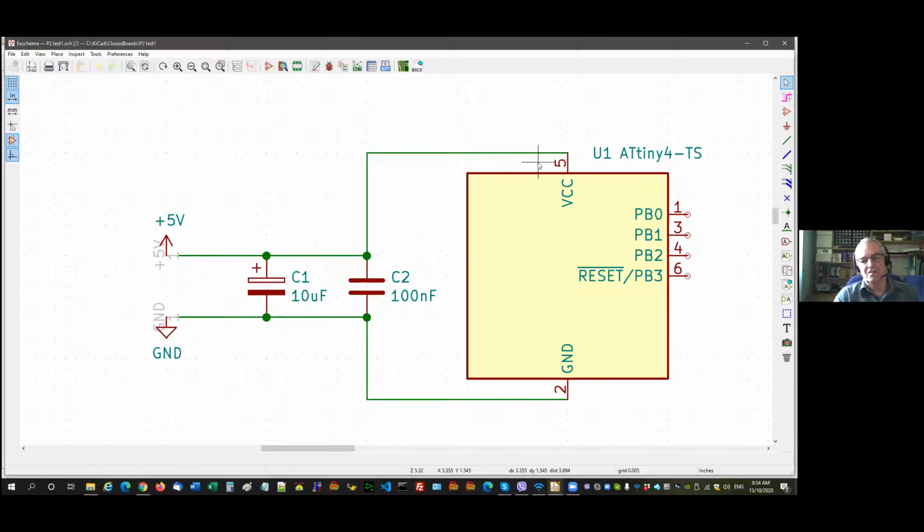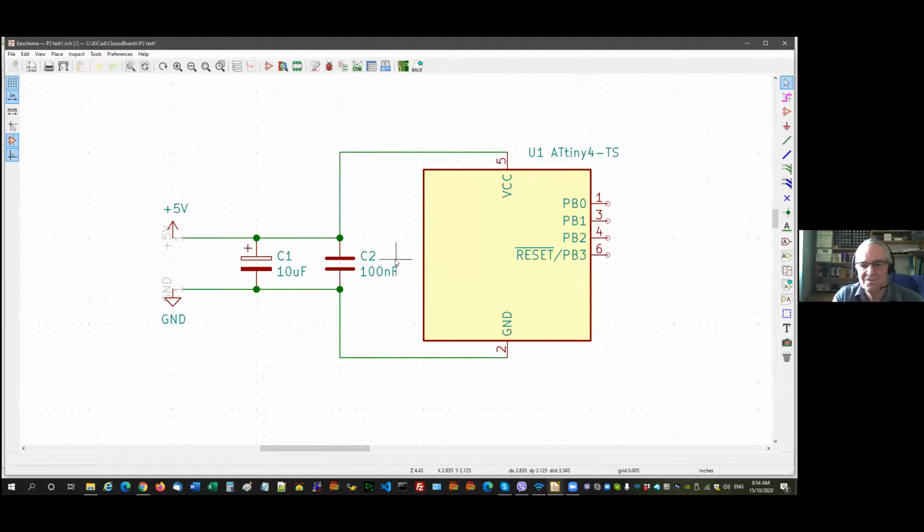So a lot of the fundamentals say this cap should really be 10 nanofarad, and you should have some of each. I haven't quite gone to that philosophy. I can do that in my P2 design, but I think that the hundreds will be fine. But definitely you need bulks as well.